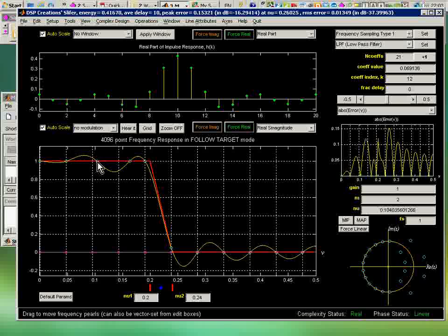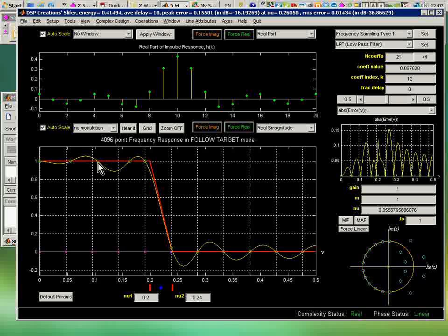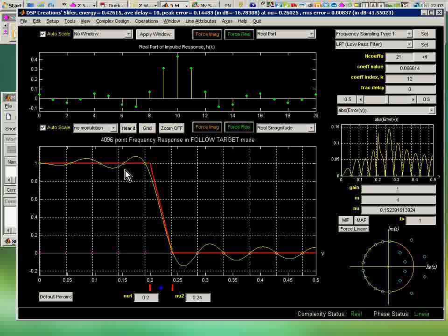And bearing in mind that equiripple filters have non-uniformly spaced extremal frequencies, well, they also have non-uniformly spaced points on the target profile. I could probably, with enough time, get myself by manipulating these things an equiripple passband, maybe also stopband.